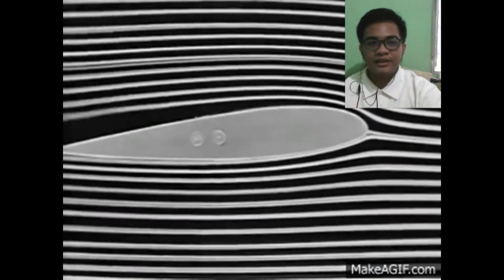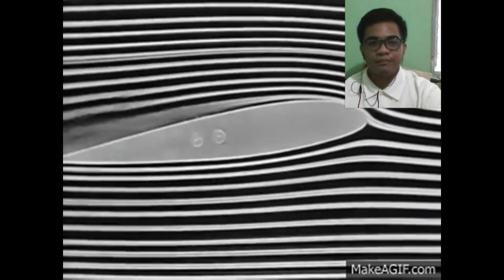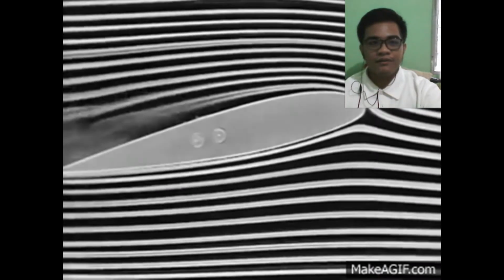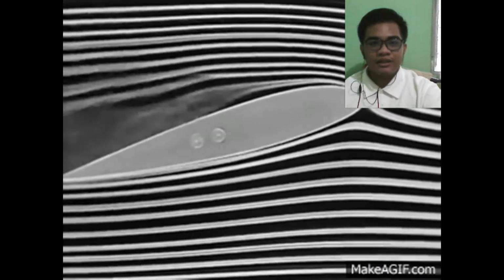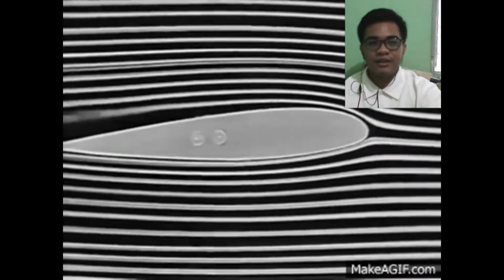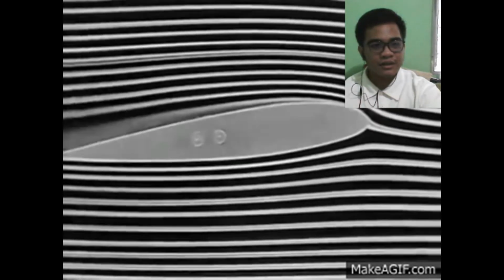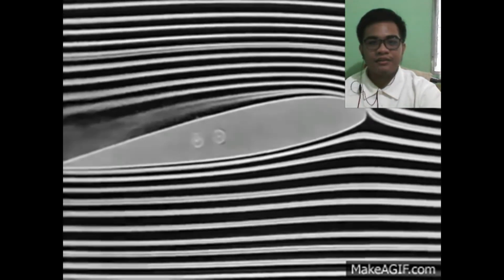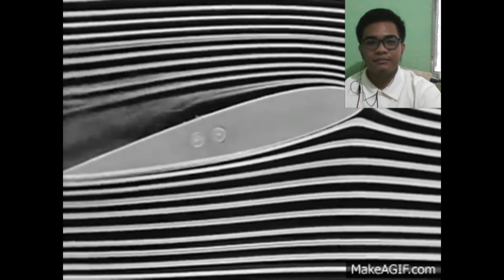When air strikes the lower flat surface of the wing, it is forced downwards by the angle, which in turn causes a counterforce that pushes the plane upward, while some of it goes towards the upper curved section of the airfoil, which causes a reaction when the air is rebounded downwards, which in Newton's law provides an equal reaction, forcing the airfoil upwards.